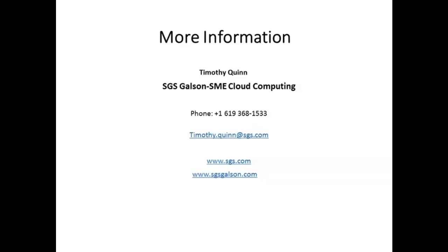Okay. So in our case, well, let me back up. Most new companies or companies that are coming out with these devices do not calibrate them ahead of time or have the ability to field calibrate. Our SmartSense device is pre-calibrated with gas prior to going out, and we have the ability via the cloud to do field calibration. So no, there's nothing that needs to be done by the end user.